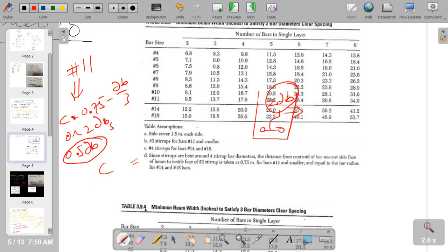This 2 times the diameter of the bar is important, because when we change this, the equation of the development length changes, and if you decrease this spacing, it causes an increase in the development length, and then it is difficult for us to adjust the longer development length.